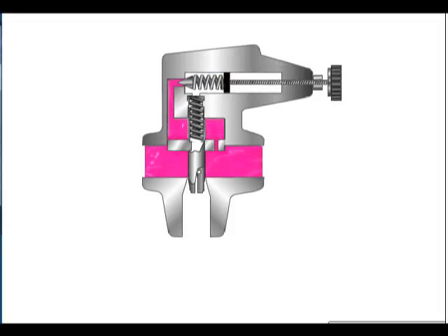Relieving action through the main spool is as follows. As long as the system pressure is less than relieving pressure set on the control knob, pressure in the main spring chamber is the same as pump line pressure because there is no flow through the control orifice, and consequently there is no pressure drop from one side of the orifice to the other.